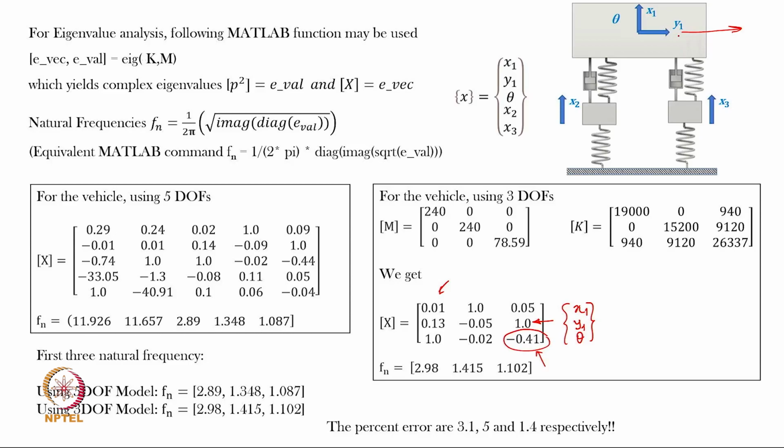Okay. So, we can expect physically, you can see that if the surge takes place along the direction of motion of the vehicle, it is natural to expect a pitch to happen, and that is happening here, because in this case non-zero value of this theta actually means in the mode shapes. These are all mode shapes, right.